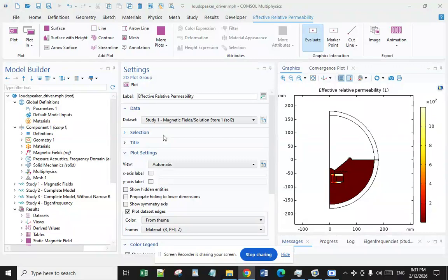The spatial distribution of Lorentz force determines the precise nature of the elastic disturbances and how they propagate from the source. A majority of successful electromagnetic acoustic transducer applications are based on the Lorentz force mechanism.